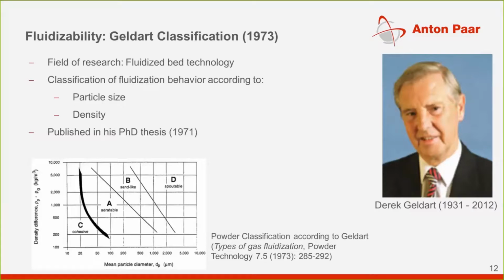And for this, we look to Derek Geldart, who was a researcher for fluidized bed technology and did fundamental research in this field. In his PhD thesis, he published a way of classifying powders by their fluidization behavior. For this, he looked at the relation between the particle size and the density difference of the particles and the gas which is used for fluidization. With this, he classified the powders into 4 groups of different behavior. The resulting publication in 1973 is still one of the most cited works in the field of powder and granular media.